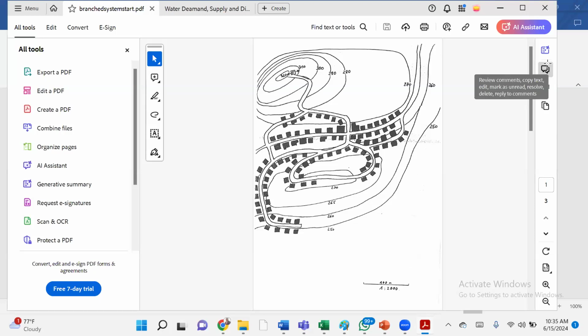All I need to do is number every node. Then I'll start from the bottom, the least node, the end nodes, and I'll start coming inside until I get to the start tank. You get the point? When I finish and I have those 4 values, I will go back to the detail in AutoCAD and assign them. I won't write the diameter, but I'll put a sign for the diameter. I'll say Q equals so much, 25 mm at slope 0.25, then invert level here, invert level there. That's a typical water infrastructure design. It's just for you to put in the values you got from those tables. That's why I expected many of us to fill those tables.